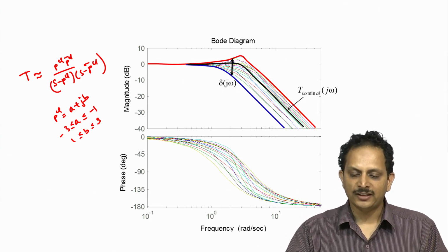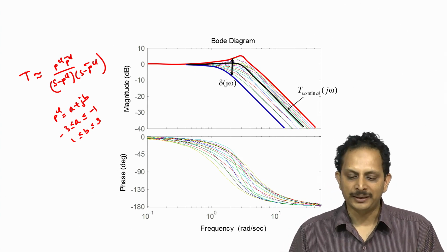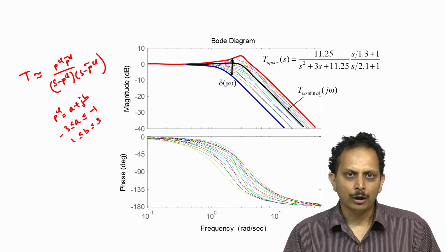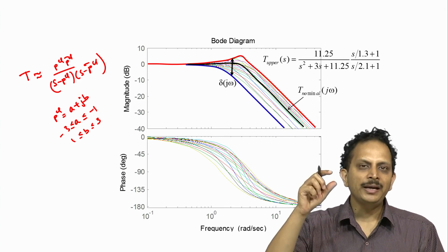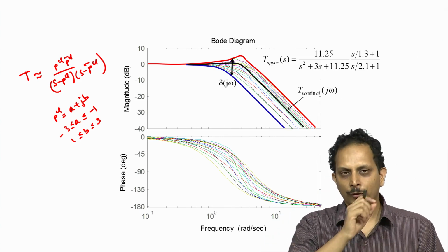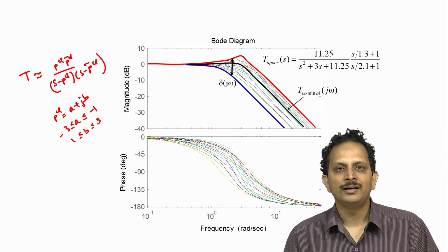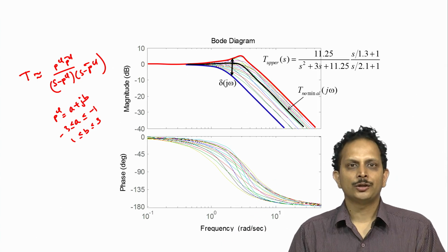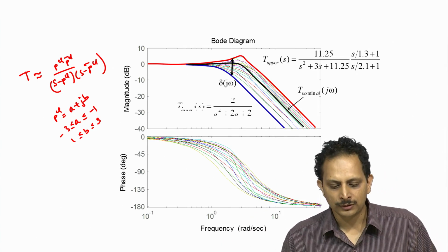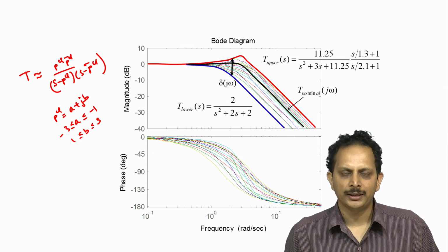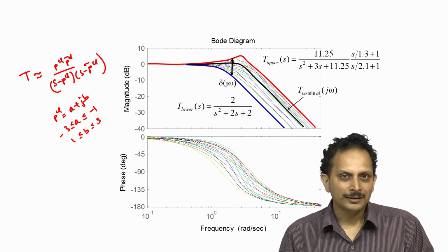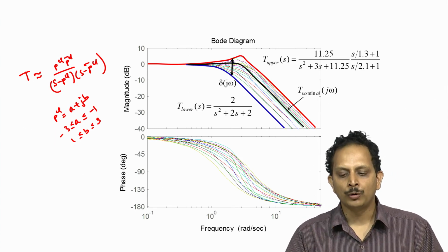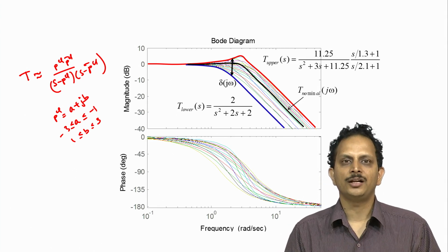Now we can obtain the exact numerical expression for the upper limit, which is indicated by the red trace, with some trial and error, but also by making note of the fact that there will be a particular closed loop pole location for which the corresponding Bode plot will define the upper limit of the variation of the closed loop pole, and likewise we can also obtain the expression for the lower limit of the permitted variation, starting from the fact that there will be a certain closed loop pole location PCL for which the Bode plot would define the lower limit of the permissible spread in variation.